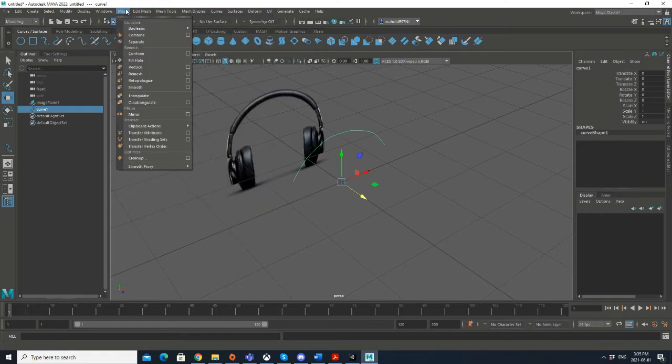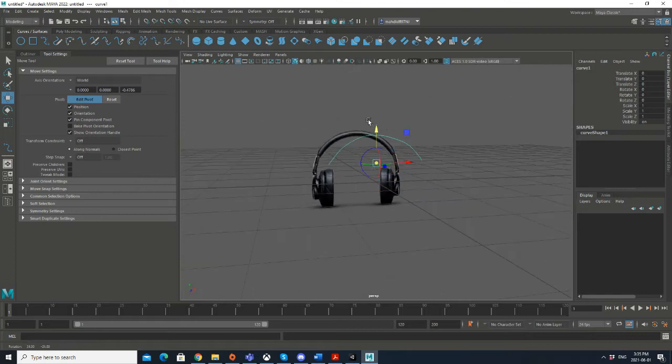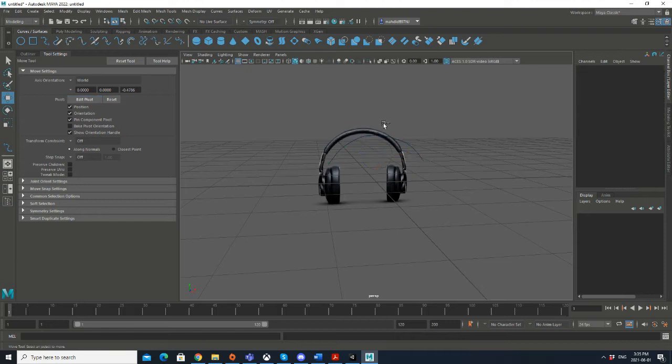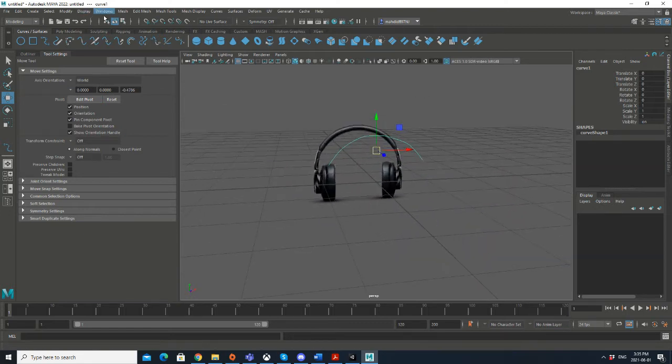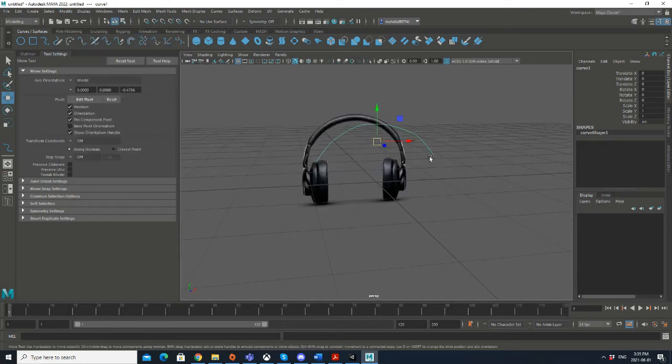Let me just find that. Maybe it's not there, but what you can do is go to the move tool in tool settings and then edit pivot. Press and hold D, I mean, or go to edit pivot. Move it upward as you wish to position it relatively in the center. I remember, yeah, in the modify menu, I found it. There is also a center pivot option there as well,